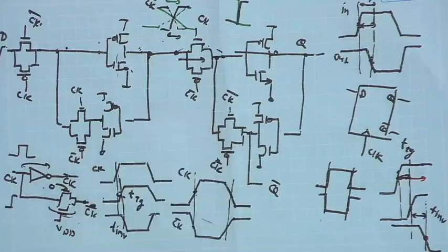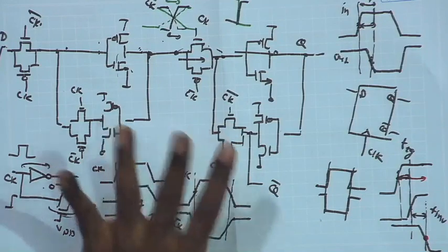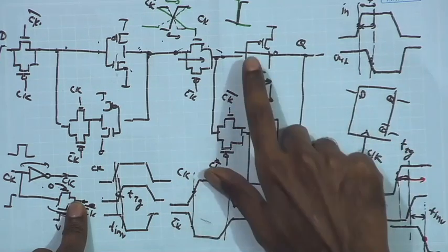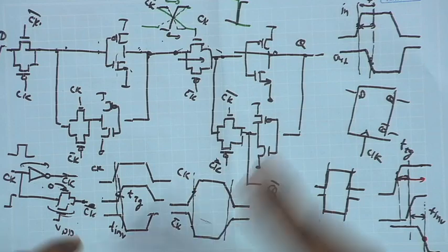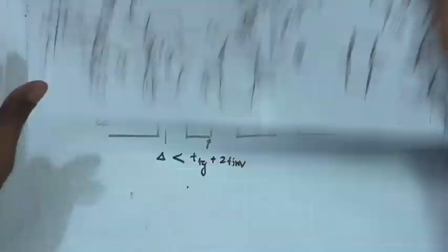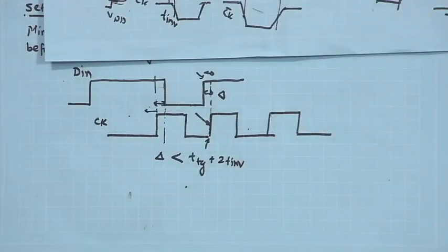Let us continue with the discussion from where we left. Any question regarding these three definitions? In our case, of course, the important criterion is the delay, the C2Q delay, because we are looking at the ripple counter. C2Q delay can be important. If we look at the setup time, however, if we look at the counter operation, are we concerned about the setup time in our ripple counter?